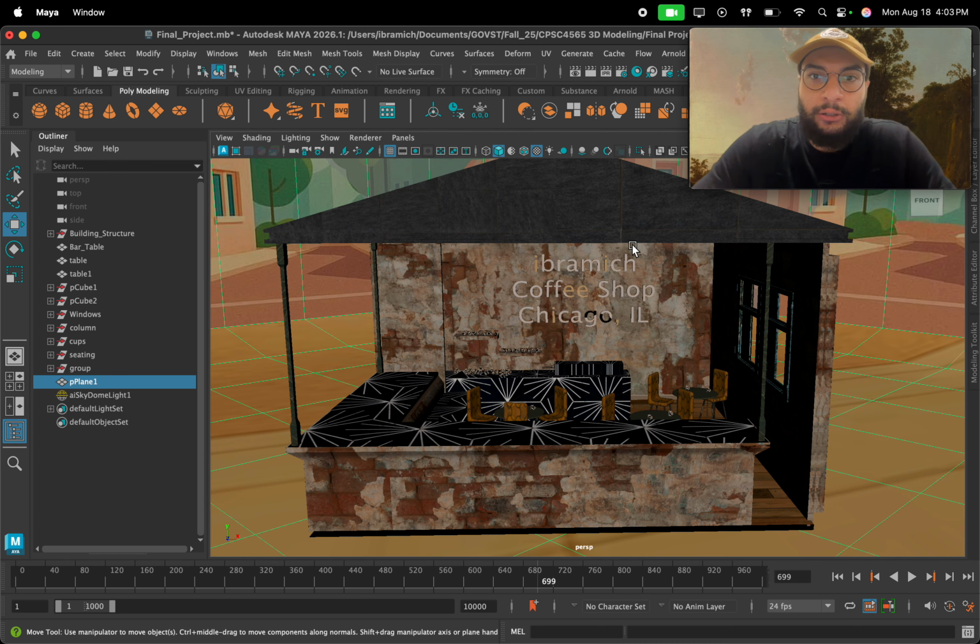I'll convert to face view. I have to make a selection, and then I'll go ahead and extrude the back out of this chair. Make sure I only have what I need selected. Yeah, the back is not selected. Go ahead and hit the extrude button. Just like that, I have my back support. Let's get this out of here.